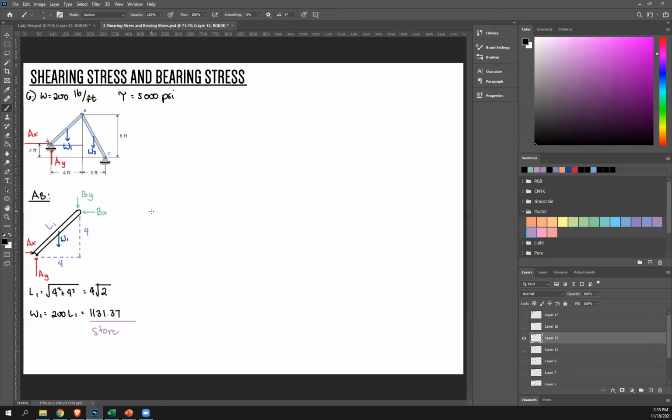So you should approach it in a way that it's easy to solve one of the unknowns. And usually, you're solving for a joint that has two members attached to it, because that means you can create two equations from it. Two equations, two unknowns, you can solve. And that joint is joint B. AB attached to it, BC attached to it, you can get two sets of equations to figure out BX, BY. Now, knowing that, I have to start with summation of moment at A to get the two equations for BX, BY.